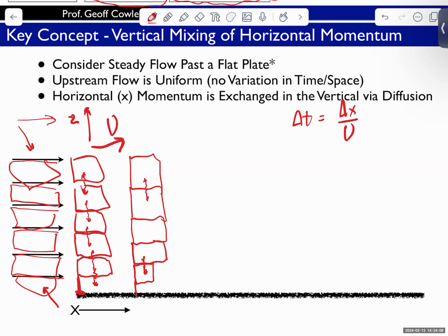But this second parcel here is still exchanging momentum with the zero momentum parcel here. And this will give rise to a slowdown. If this is number 3, 2, and 1, this means now 3 is going to be slowed down. Sorry about the delay. It's going to take a second here to appear. 3, 2, 1. And so sometime later here, we have still 0 at the wall, or a slower 2 parcel. 3 has now been slowed down. And number 4 is still as is. And you can kind of play this game forever.